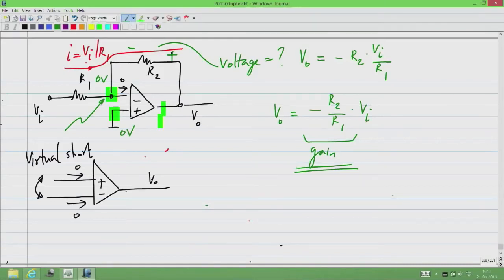Now I will go through the conditions under which the op-amp input will behave like a virtual short. Now the resistor could be at the non-inverting terminal also, but we have to see. It depends on the topology. There are numerous topologies of op-amp circuits, and some of them have resistors only to the inverting terminal, some of them to both inverting and non-inverting terminals.